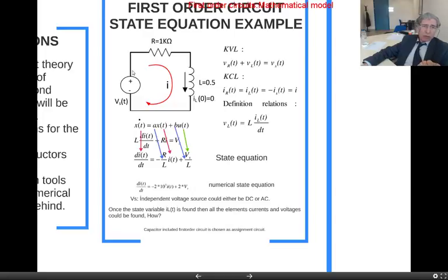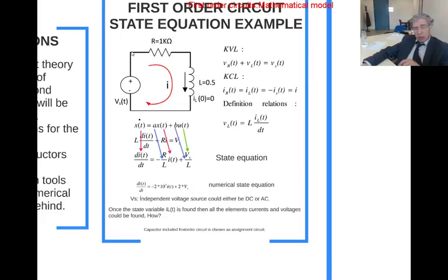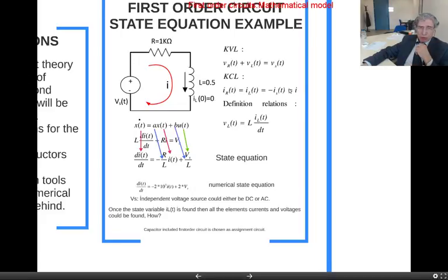And the independent voltage source current is negative to this one. Why is that? Because according to passive sign convention, the current reference is downwards. So the current reference in here, if we assume this one, is both of them coming out of the node. So one of the currents has a negative sign, the other current. So this is what I said.